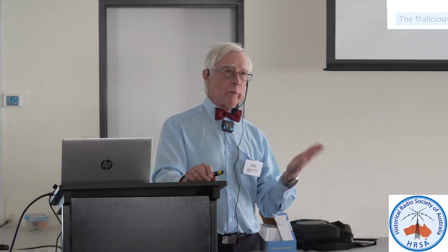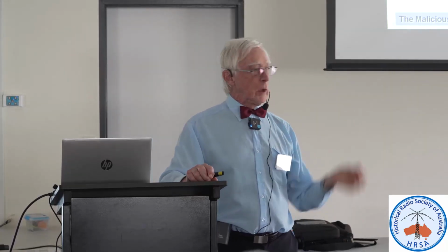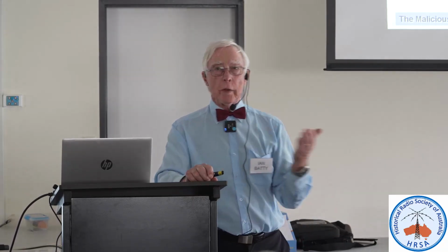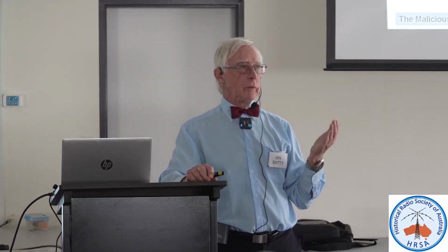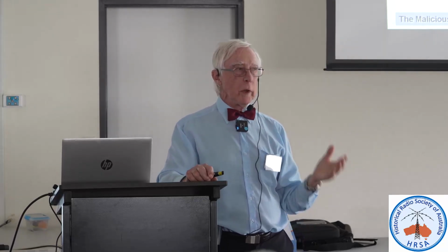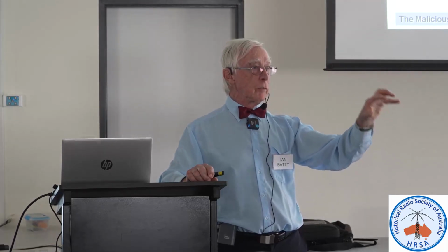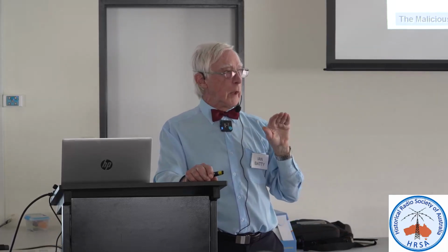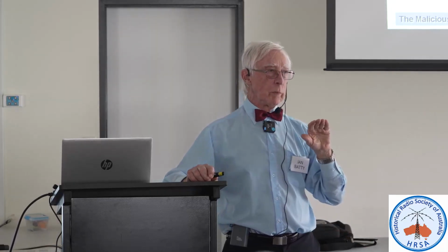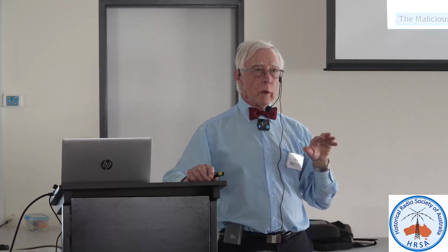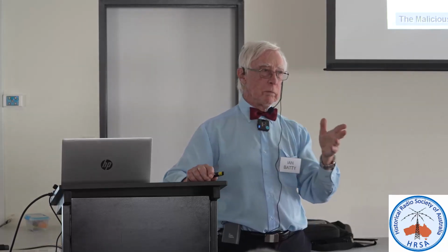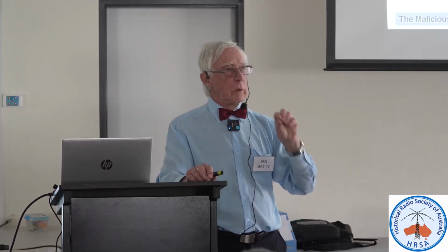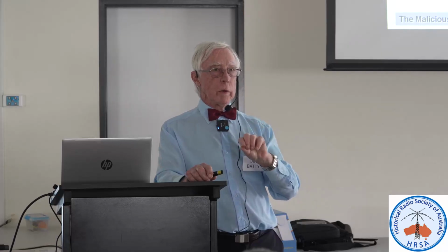I was going to talk about recapping, but I'll do it now. Some people just go, going to recap. And I understand that because what you've done is you've replaced the components that are most likely to be faulty. And some people will go further, they'll get a new kit of new valves or valves they've tested, dig out all the old ones and put in new valves. And they know that they've removed the components most likely to cause faults. I've got a more sort of back-to-front approach, so I don't tend to do that. The advantage of recapping is you know that you've removed the most likely component to be faulty.